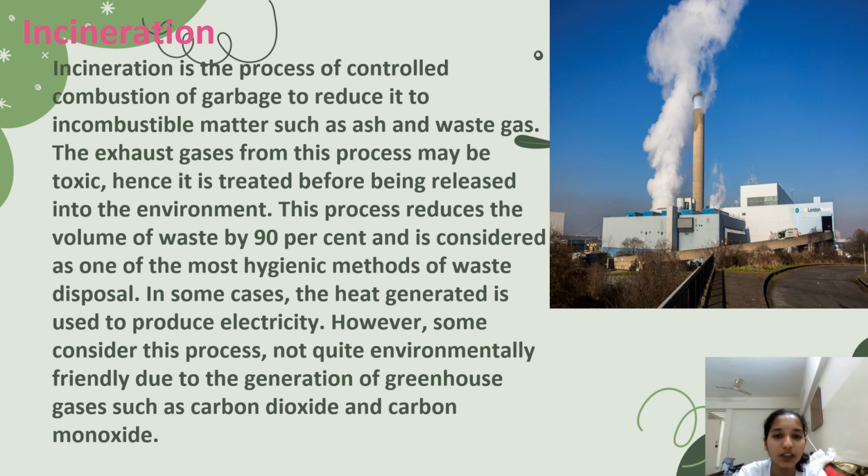Incineration. Incineration is the process of controlled combustion of garbage to reduce it to incombustible matter such as ash and waste gas. The exhaust gas from this process may be toxic, hence it is treated before being released into the environment. This process reduces the volume of waste by 90% and is considered one of the most hygienic methods of waste disposal. In some cases, the heat generated is used to produce electricity. Some consider this process not quite environmentally friendly due to generation of greenhouse gases such as carbon dioxide and carbon monoxide.